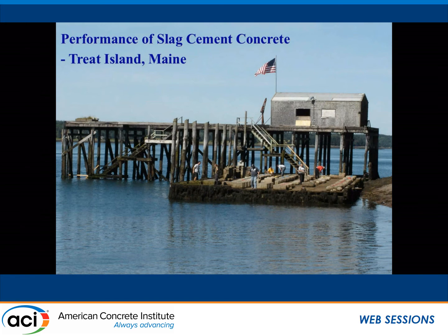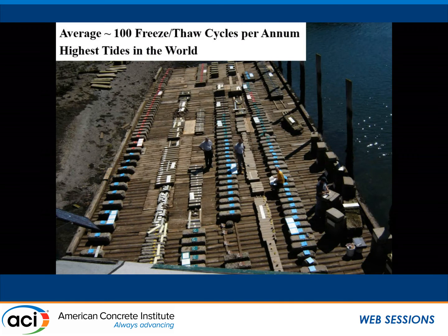We do have some data from Treat Island. With ternary mixes, only a little bit of data. For those of you who don't know, Treat Island is an exposure site. There's a wharf at the mid-tide level. It's an exposure site that's owned by the U.S. Corps of Engineers. Highest tides in the world is a 20-foot tide difference, daily tide difference, so it's a really very aggressive condition, about 100 freeze-thaw cycles per year as well.